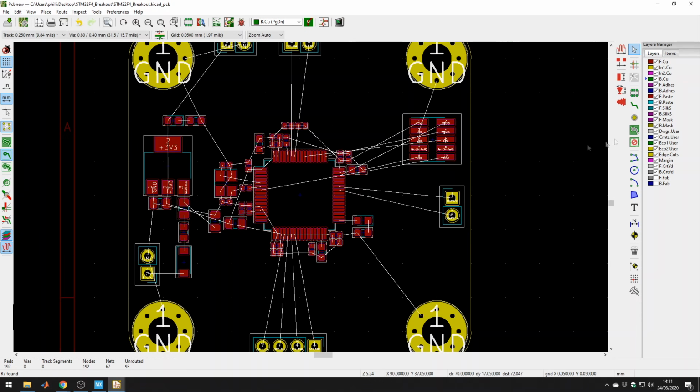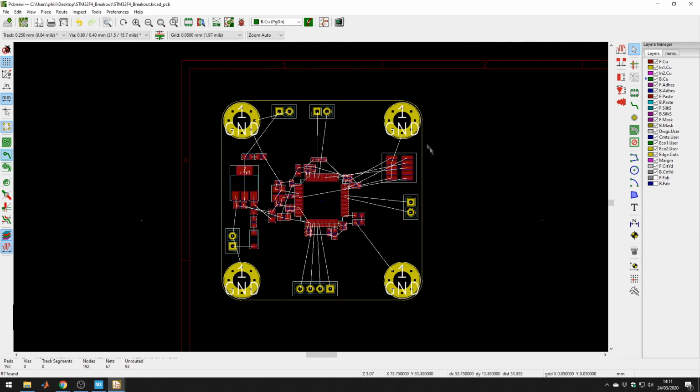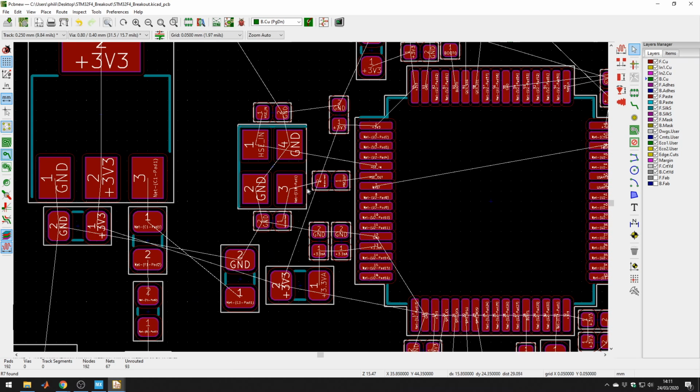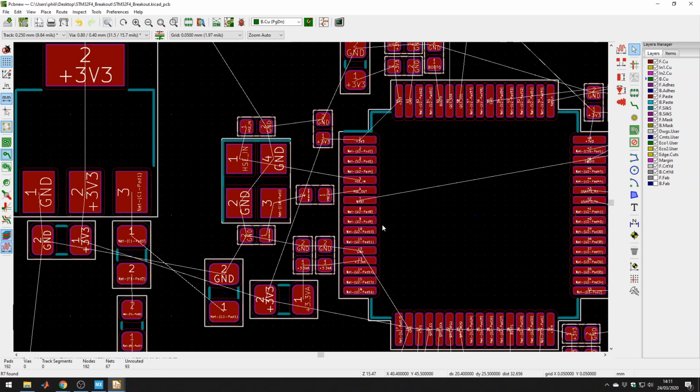An important thing now is we want to essentially fill the whole thing with copper except underneath the crystal oscillator. Now the crystal oscillator needs its own single ground plane, and this ground plane is attached at only one small trace to the rest of the ground plane. We want this as isolated as possible from the rest of the ground. So let's do that.